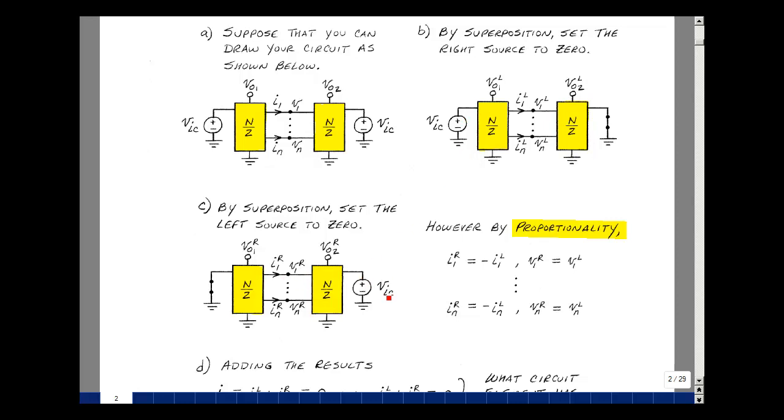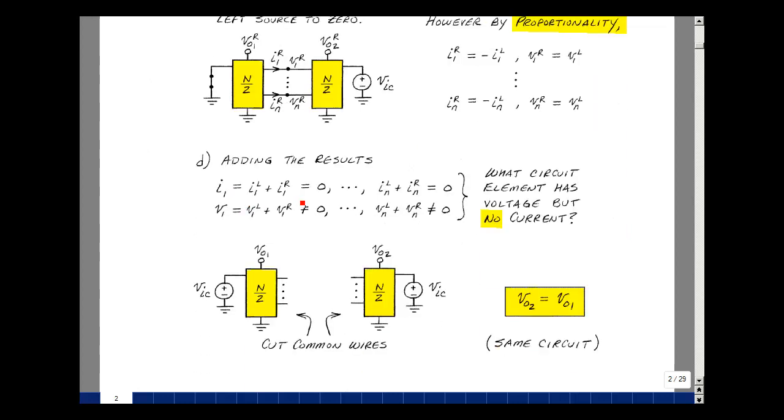With the same amplitude, I'm going to multiply the previous results by a +1. I'm going to have the opposite direction of current here that I did over here. Again, looking at the circuit this way and looking at it this way, that same current is in the opposite direction. By adding up those, they're going to cancel each other. All the currents are going to sum to 0, but the voltages will be whatever they need to be.